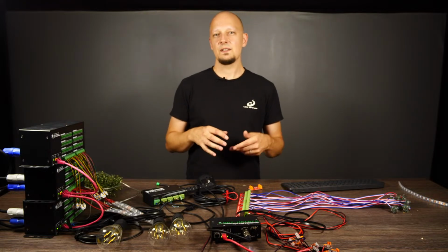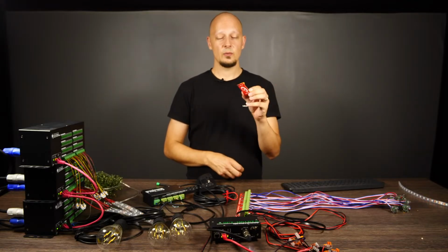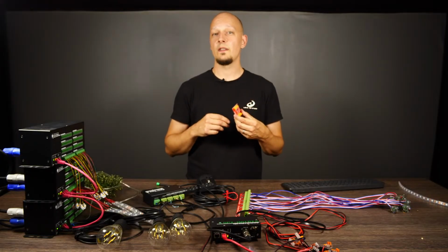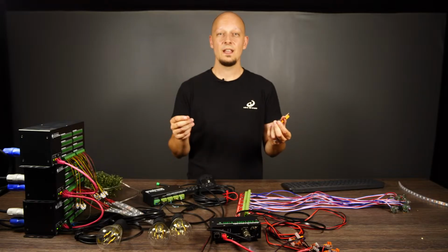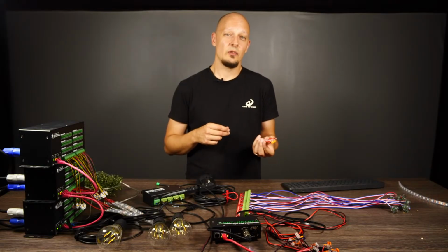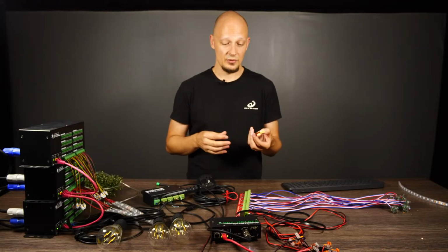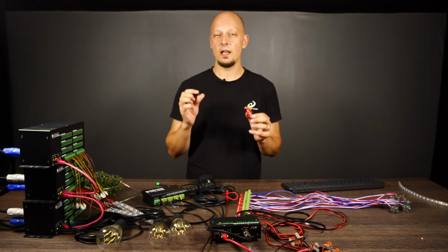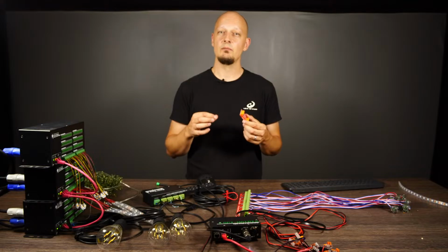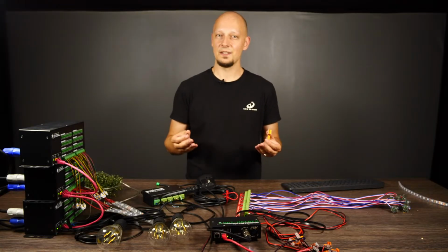What I wanted to tell by this, again, this is subject to a test, whether you will be working with the 24-volt version or a 12-volt version. It can work with some LED strips on even 20 meters, and then you will have another strip, another batch. Perhaps the quality of the production will be lower, and you'll be experiencing issues even on 2 meters. So that is why it is always a good idea to have some of these as spares available, and you can install them, and most probably it will help you on not that long distances.